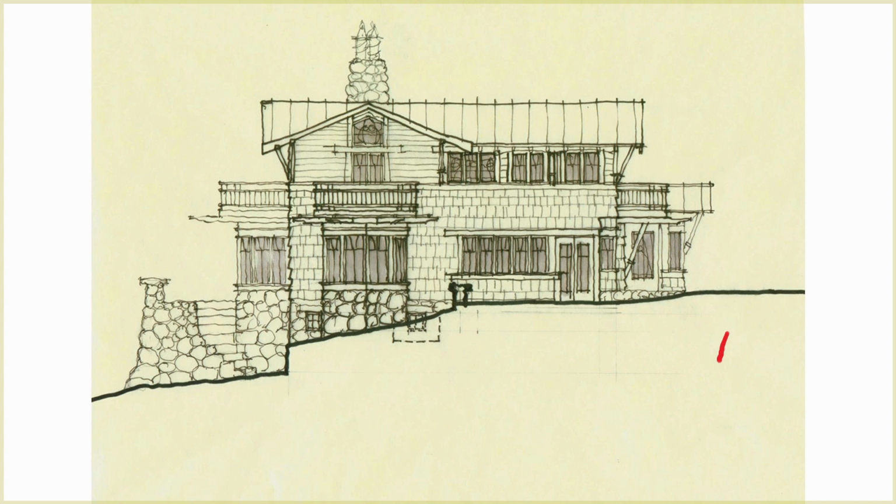The ground line, the cut line. So this line here is the darkest line. That tells us where we are cutting the ground to look at this elevation and what's happening with that ground. So whenever it's a cut line, it's always the darkest line. As you squint at it, what would be the next darkest line? It's a little bit trickier to see. I think it's in two places.